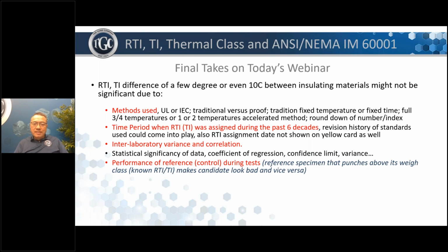One thing I'd like to mention is that UL follow-up surveys, because RTI takes so long to do, are never part of the UL follow-up survey. They would do fingerprinting, they would do flame, sometimes HWI, HAI, short-term properties, and that's it. They would never retest your long-term properties. So you have no idea how long ago the RTI number came from, or on which revision of the standard it was tested against.